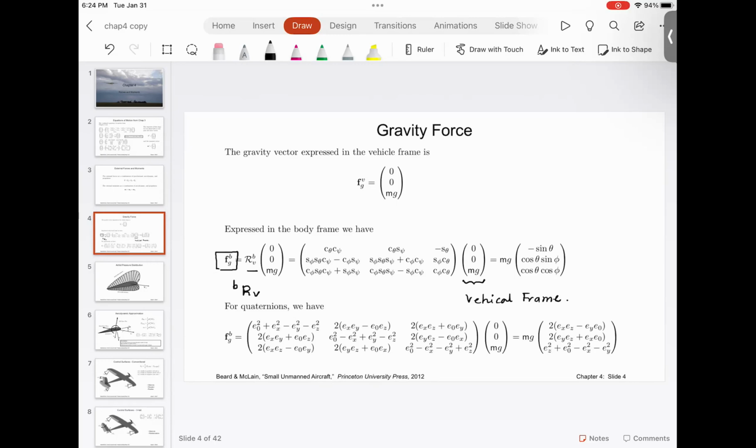Once you translate the inertial frame to the center of gravity of the aircraft, you have the vehicle frame. Vehicle frame and inertial frame have a pure translation relationship, no rotation. From vehicle 1, you have vehicle 2, and then finally you have the body frame. Then you have the stability frame, and then you have the wind frame. Remember all these frames?